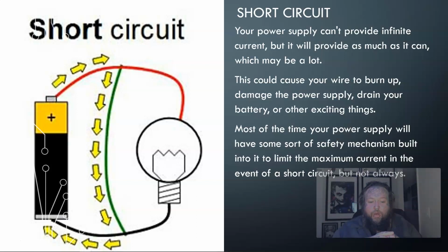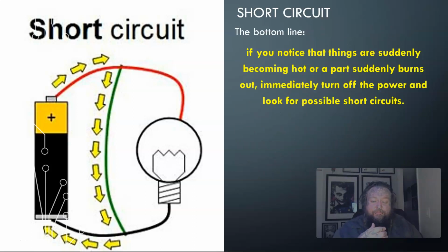This could cause your wire to burn up, damage the power supply, drain your battery, or other exciting things, sparks, like you don't know. Most of the time, your power supply will have some sort of safety mechanism built into it to limit the maximum current, which is okay, but you still want to be careful. So the bottom line: if you notice that things are suddenly becoming hot or a part suddenly burns out, immediately turn off the power source.